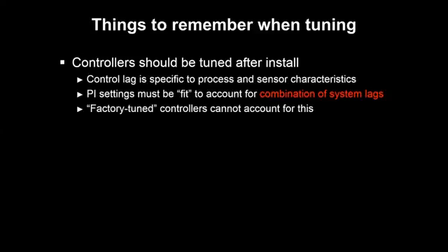So a few things to remember. First is that controllers really need to be tuned. You may hear things like a factory tuned controller is good to go out of the box, but one thing we want to stress is that you have these systems of lags. If you have something like a pipe sensor probe that's in a well, in a piece of pipe, you can imagine there's a certain thermal lag associated with that, and you want your control system to be tuned to handle it, so that it's not constantly overshooting or cycling or not accounting for that specific set of lags in your system.